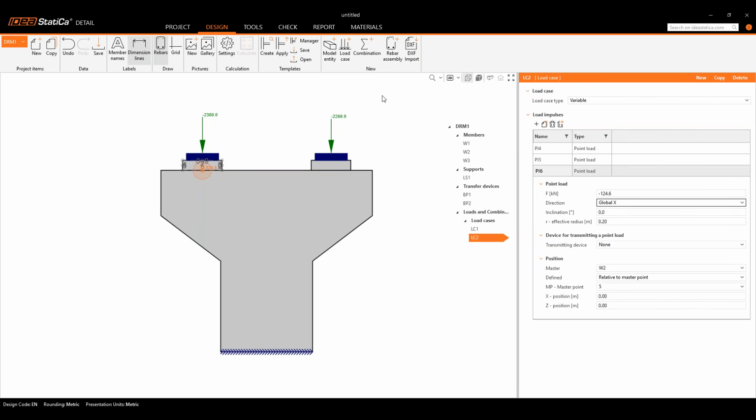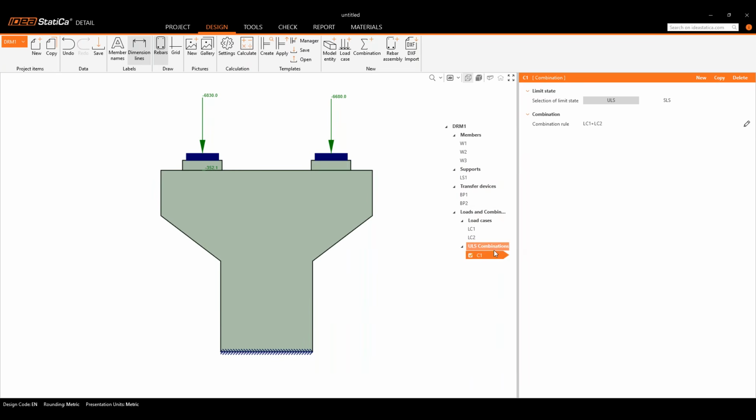So now I'm going to create a load combination. I'm going to create load combinations. This will be for ultimate limit state. Now I'm going to create a copy of it, but I'm going to change it to serviceability limit state. I will leave it under characteristic, but for this case, I'm going to deactivate active for crack check. So I will leave only deflection check.